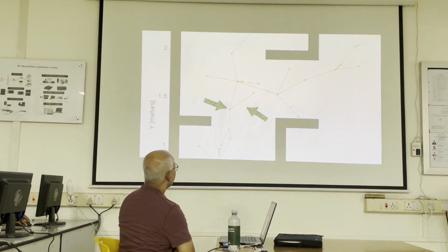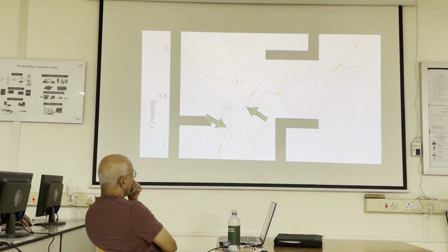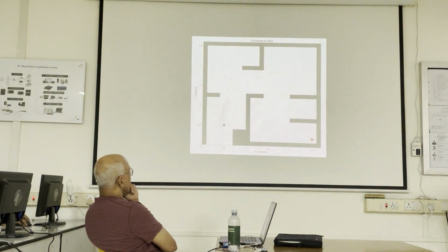But watch what happens. That node appears and it's connected all the way down here, since that's a shorter path back to the start. And it reconnected some of the other nodes within the search radius. So RRT star is always trying to shorten the paths. Let's continue. Here it reaches the goal, and just like with RRT, the path is a bit zigzaggy at first. But as we continue adding more nodes, and the existing paths are reconnected, you can see how they get refined over time, becoming shorter and straighter.